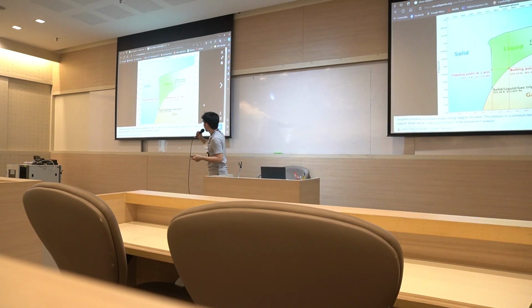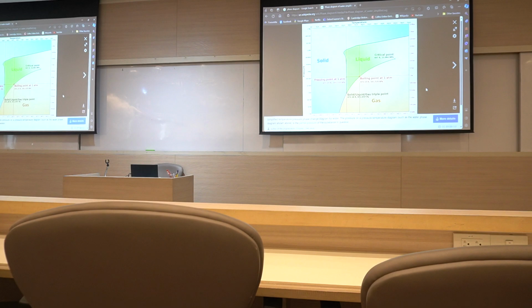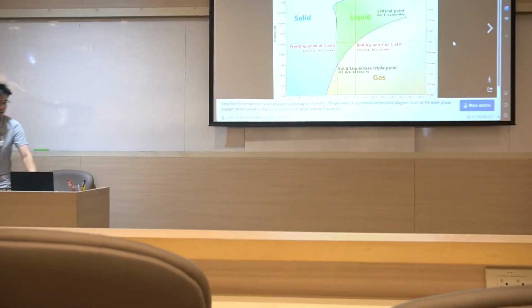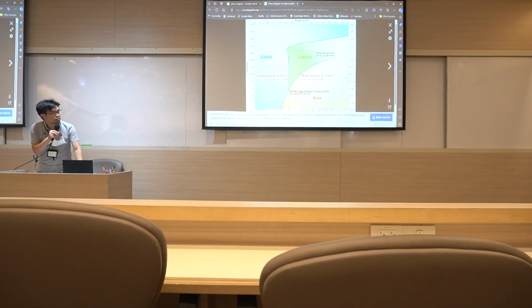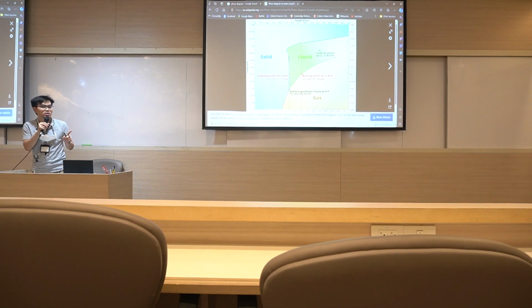High pressure, yeah, for water. Okay, so the procedure we talked about was something like starting from the vapor region somewhere here, then going vertically because we kept the temperature constant and increased the pressure, right? So we go upwards. As you can see here, we process the vapor-liquid region, so that's when the transition from vapor to liquid occurs. And as you said, if we keep increasing the pressure, we could go right into the solid region,